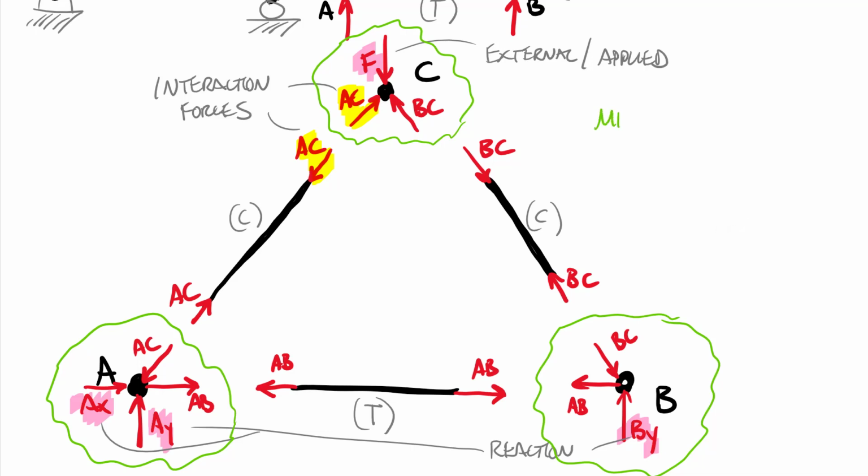So in the method of joints, fundamentally we sum forces in the x equal to 0 and we sum forces in the y equal to 0. We don't have any available moment equations because our forces are concurrent. If you summed moments about that point, you basically get the sum of all moments equal to 0, because the force lines of action go right through that point.